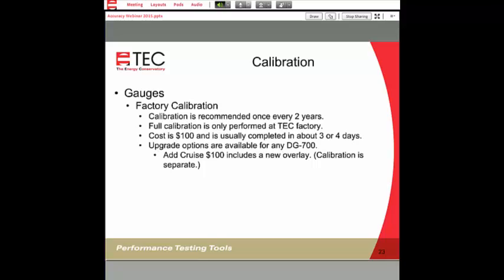We're still doing a calibration to bring that down as close as possible because we know over time those results will start to expand and you're going to get an instrument that is going to go out of calibration at some point. So we do a complete recalibration and put in all new values so that the gauge itself is going to be as accurate as possible. So we want to get it down to 0 as much as possible.